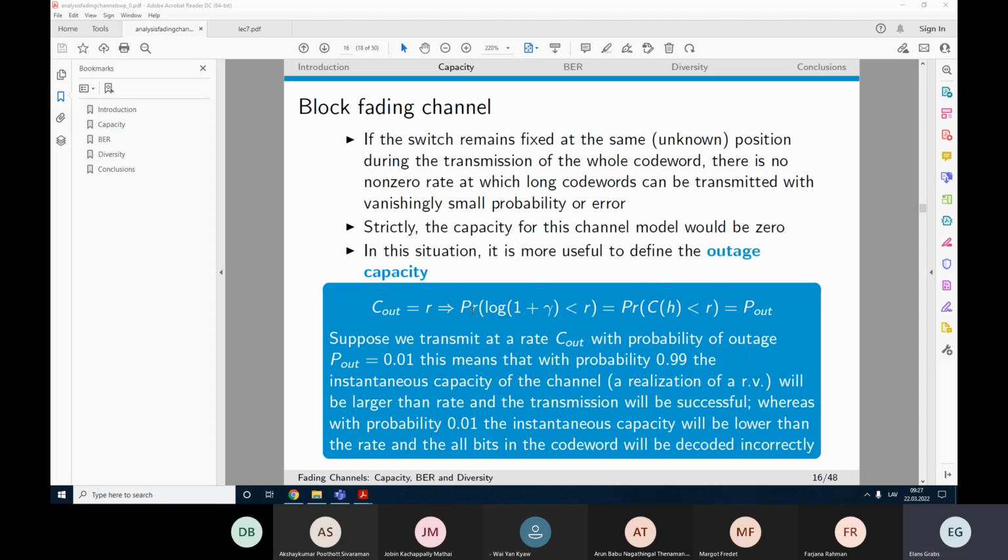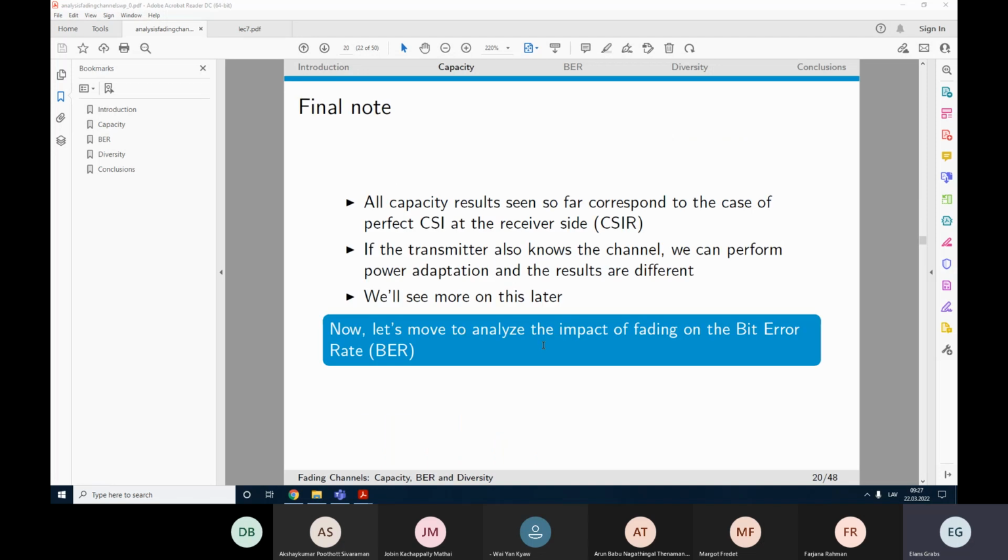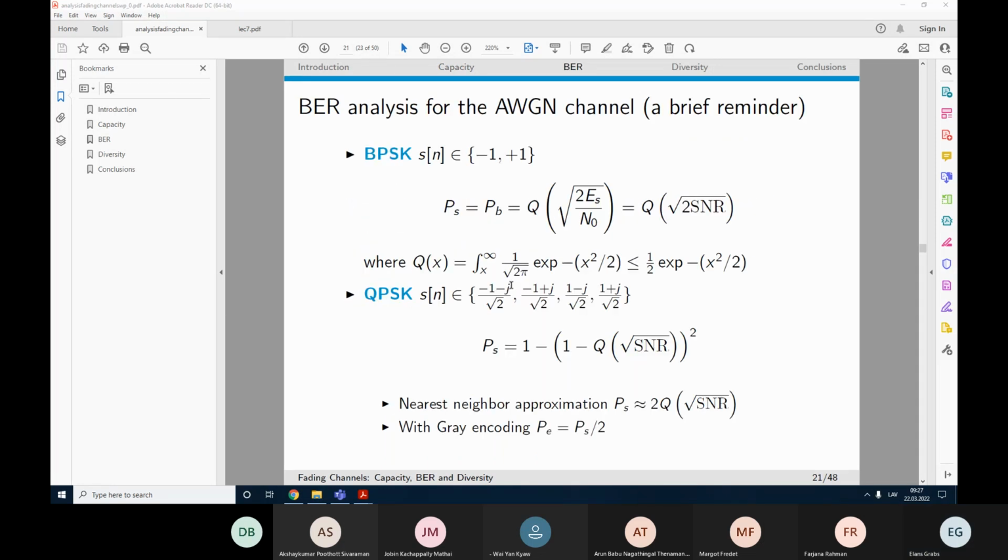And it can be accordingly expressed, yes, as a probability. Okay, so if we go further for the bit error rate, how does it change for the Rayleigh channel? Then we don't have these formulas we had. So normally for white noise channels, for example, binary frequency shift keying, we actually have some formula which we can use to evaluate the error probability, yes?